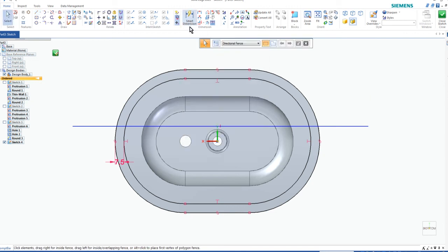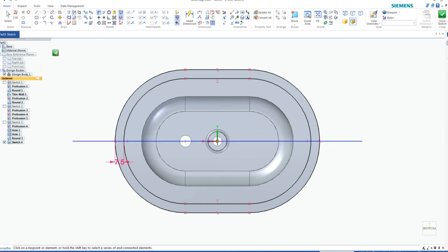Next, we are going to click on Join. We're going to pick the center of the line in the absolute center. So that produces that bisector. Now that bisector we're going to use to specifically cut and then place all of our holes. Before we do anything, hit escape.